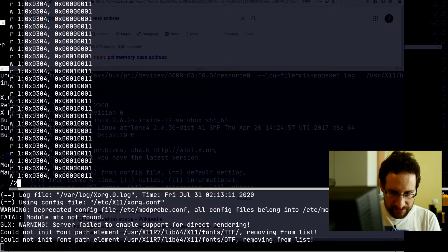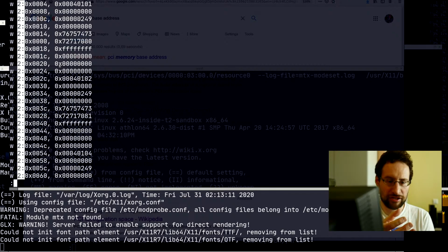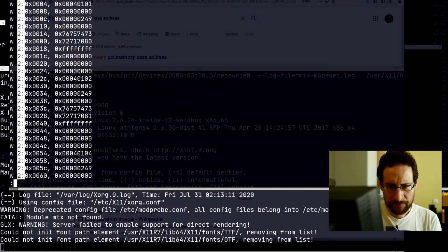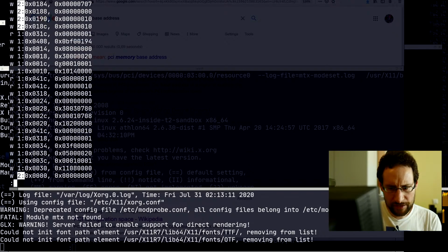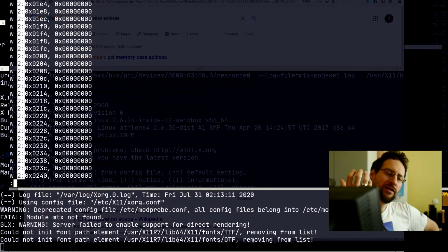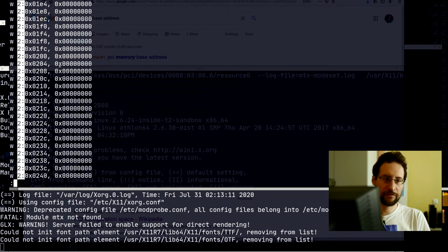And then also eventually, because we trace the memory mapped I/O region and the frame buffer, so this is the frame buffer. At least it should be, not really sure what it is doing here. So basically these are all the register reads and writes, and of course right now this is only magic numbers and we need to decipher and find some pattern, like do some human pattern matching to understand what's going on there.